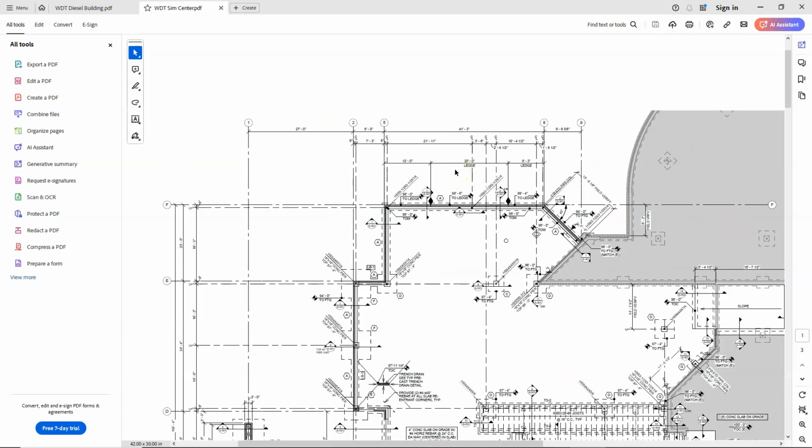So the reason we use grid lines instead of just dimensions is because oftentimes we're going to reference something. On a large complex building, it's really nice to be able to reference exactly where something is, like a column. So we can say that column E5, for example, we're going to be able to identify exactly where that is very quick and easy. Okay, so that's the what and the how, or the what and the where, I guess, and let's talk about the how next.